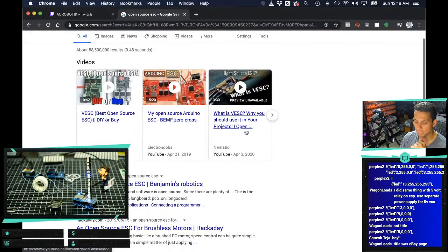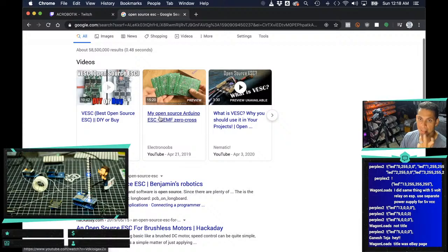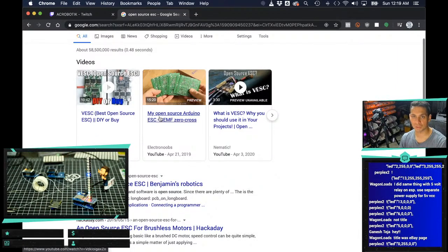They do a whole lot more than just a simple H bridge. When I say a whole lot more, you need to read a little bit into ESCs, but it's about making sure the output is linear, depending on the actual PWM, the speed on the other side, the voltage to the motors, that relationship is as linear as possible.